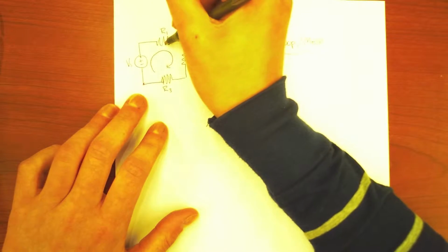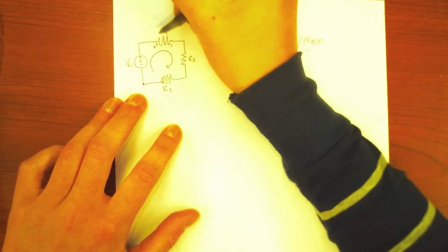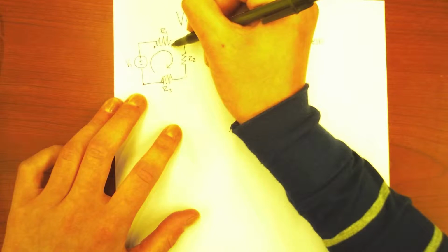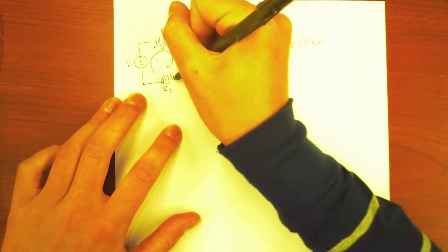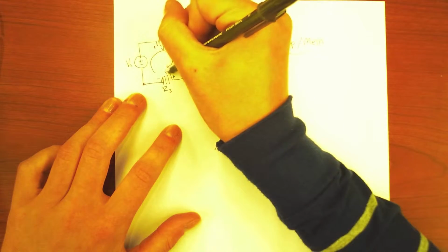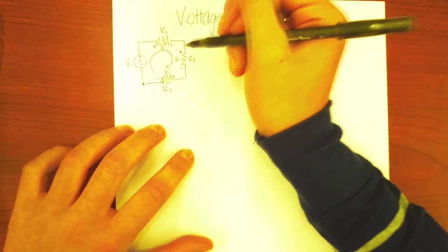Then looking at this first resistor, R1, resistors absorb energy. So whenever you're drawing your current loop, you want to automatically put a plus, then minus, going plus to minus, and you always want to do it according to which direction the current is flowing. Since we're going this way, we have a plus on the left and a minus on the right, and we're going to do that for each one. The voltage across this resistor is going to equal V1, across this resistor V2, and across this resistor V3. Now this is just notation. We haven't really done any calculations yet.